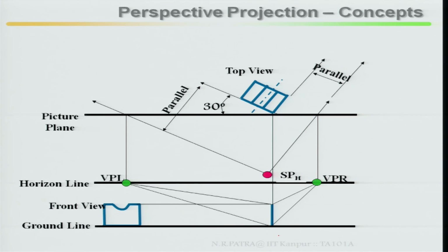First you go to your outer edge, mark the point, project it back. As I said, this gives your left face. So you mark this, then go to the inner edge of your left face, then project it back, then draw it. Then there is a center line as well as a circle or hole here, we do not know.